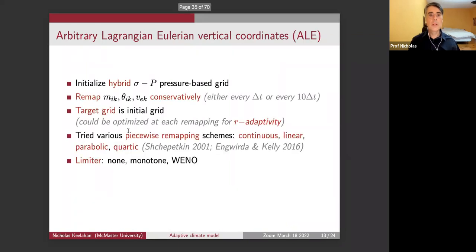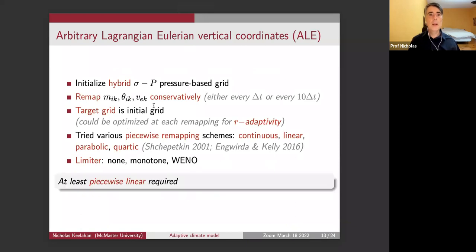Now, I'm just going to do this fairly quickly, but I said in the 3-dimensional case, we have these different layers. So we stack up our shallow water equations in many layers, and there's 2 choices for a coordinate system: Eulerian, where the coordinate system is fixed, and Lagrangian, where it moves with the flow. In other words, the coordinates follow these interfaces between the layers or material surfaces.